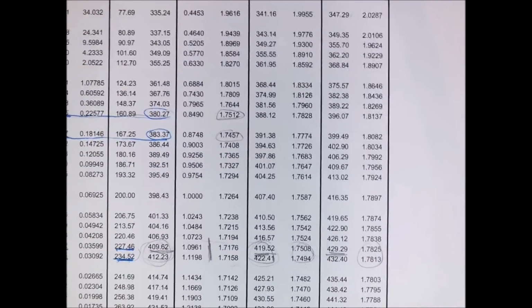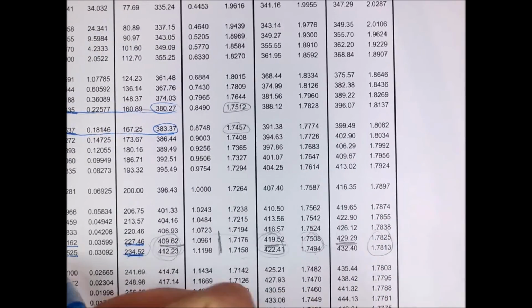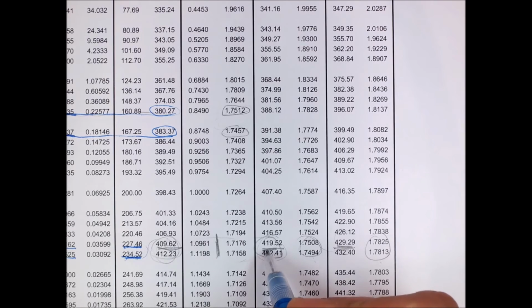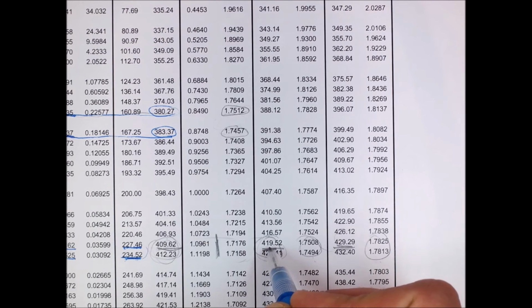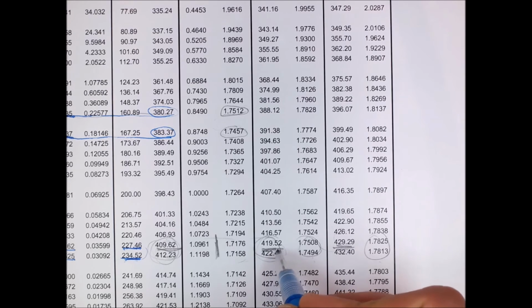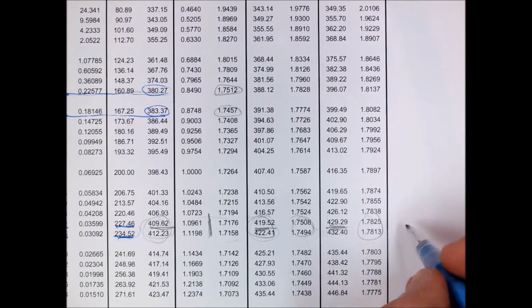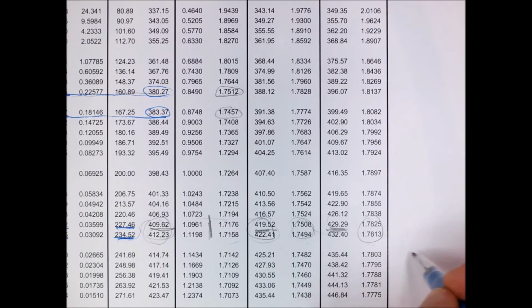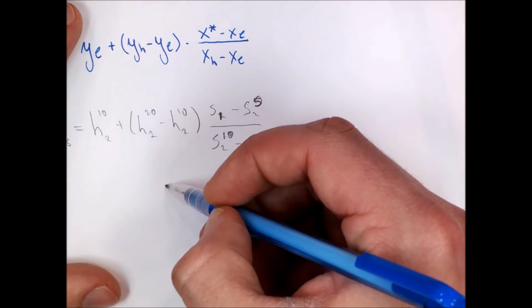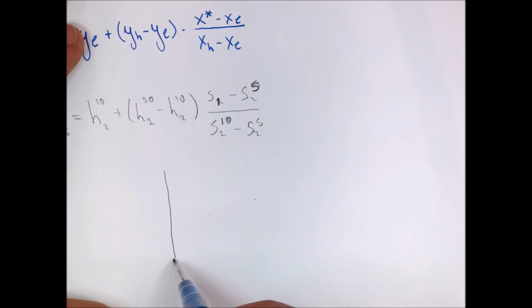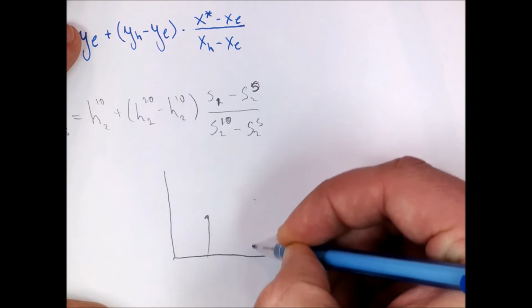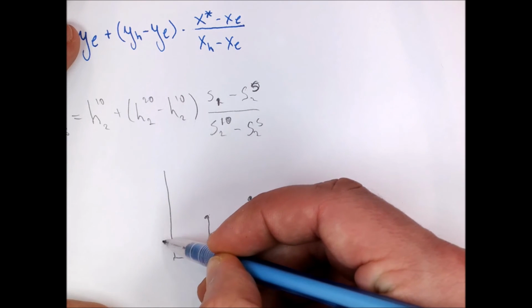Now what we need to do is say, okay, we know how to find the enthalpy at 10 Kelvin superheat for 6 bar. We already did here. We know how to find the enthalpy at 20 Kelvin. But now we know that our superheat actually lies somewhere outside of the table. It's 32 Kelvin. Well, that is not a problem, because since we're assuming linear interpolation, we know the values at these 2 points, and they're spanned by a line.